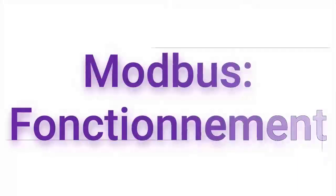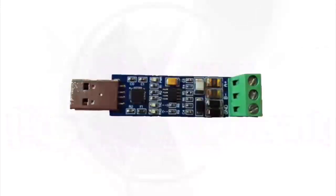Let's look at a concrete example. Here we take an RS485 and USB adapter to communicate from a computer with Modbus equipment. The computer plays the primary role. Looking at the green part, we see 3 connectors. One is ground, and 2 others make up the RS485 bus called A plus and B minus.